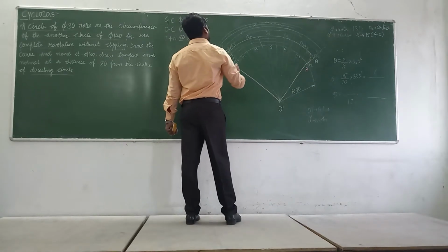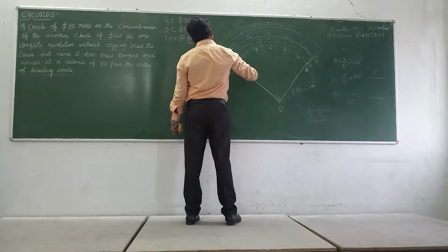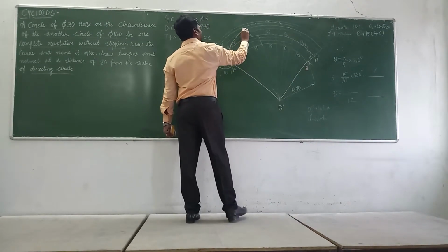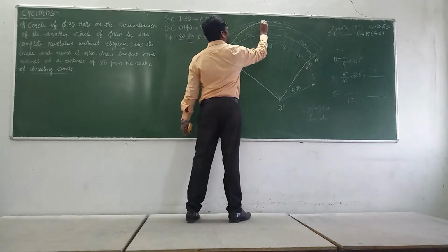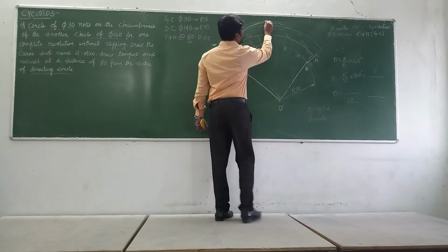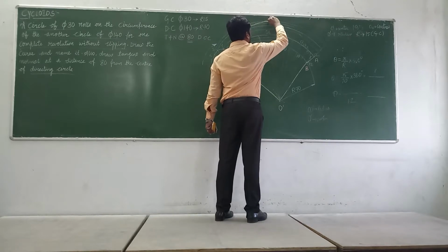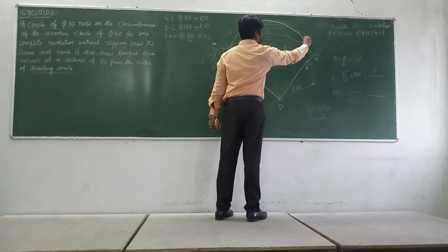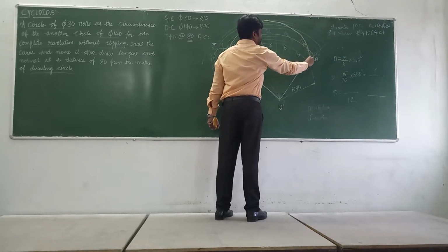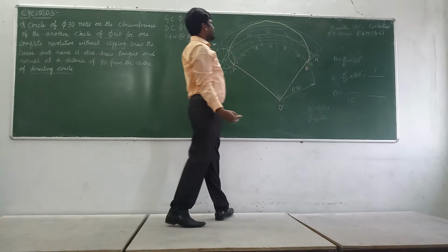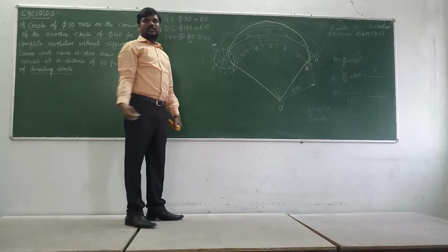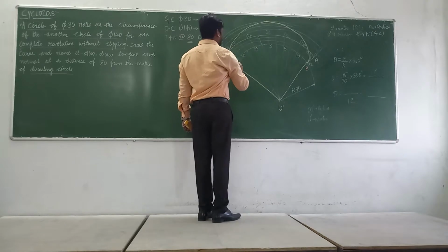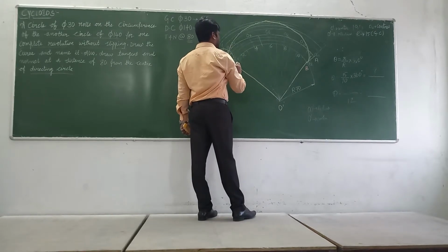So dear students, now with an HB pencil, in a single stroke, you are going to join all these dots without lifting your hand. In a single stroke you are going to draw this. So this curve is nothing but a cycloidal curve, whereas it is moving on the directing circle as it is touching.